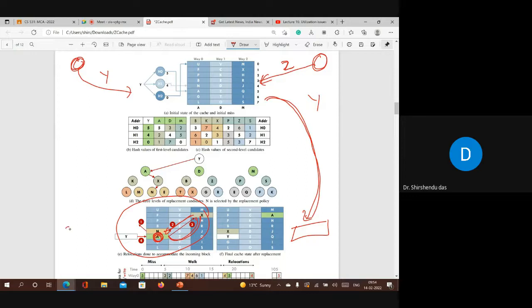If you read the paper from 2010, they assume a single bank design, and they said that this is not falling in the critical path. But in 2020, obviously this is falling in the critical path. Why I'm explaining it: maybe when you do your term paper, if you know this paper, you will try to find a solution where it is not falling in the critical path, and we can still use the concept of Zcache or skew associative cache. So Zcache and skew associative cache are important.